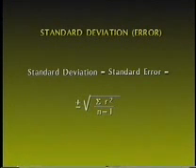The result is plus or minus because the algebraic sign of a random error cannot be determined. The sum of the residuals squared is determined by squaring each residual, then adding up the results. This formula is a standard formula used to determine the precision of any group of measurements and is developed from statistical analysis. Take time now to determine the standard deviation for the example.